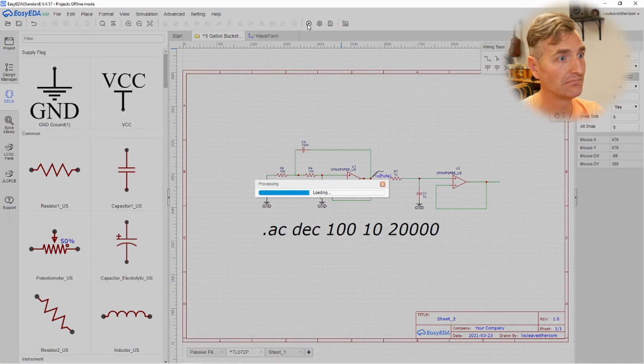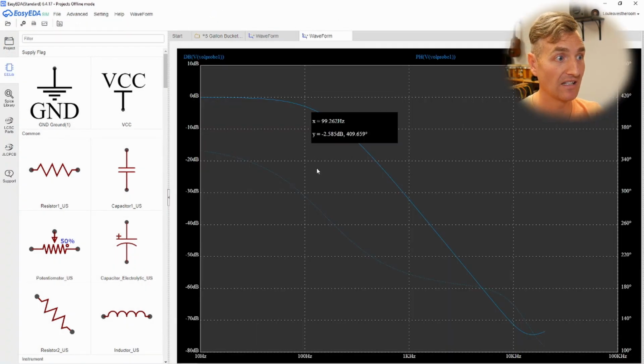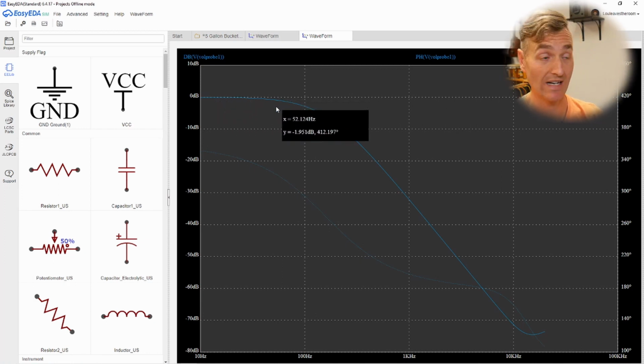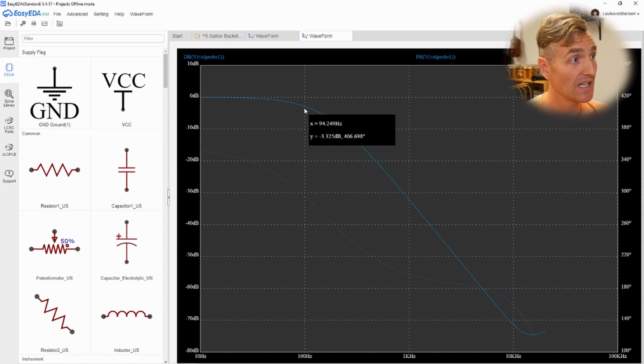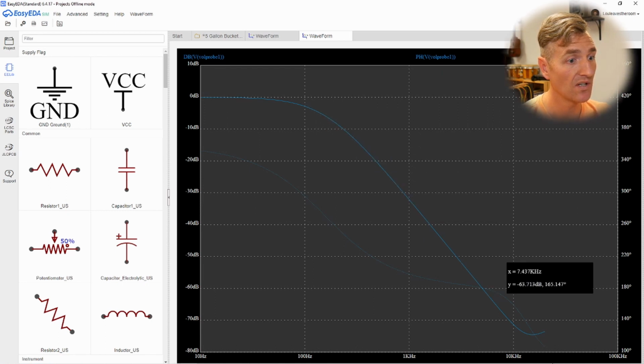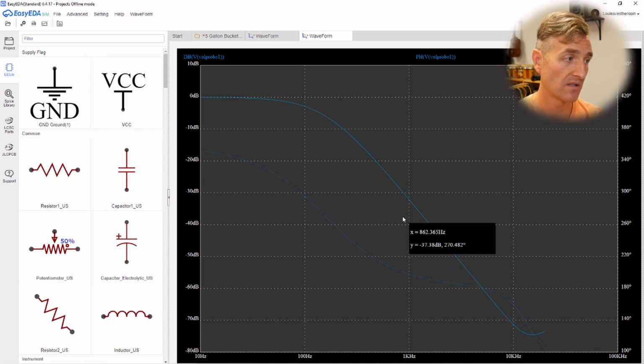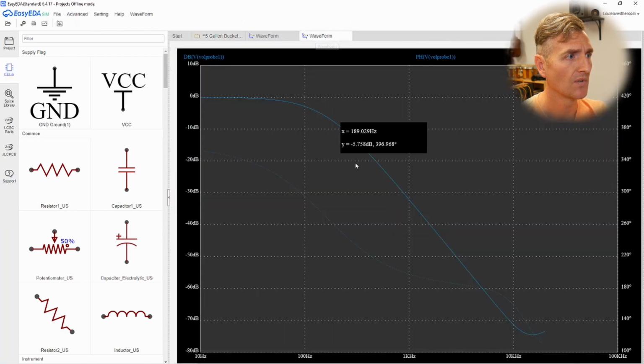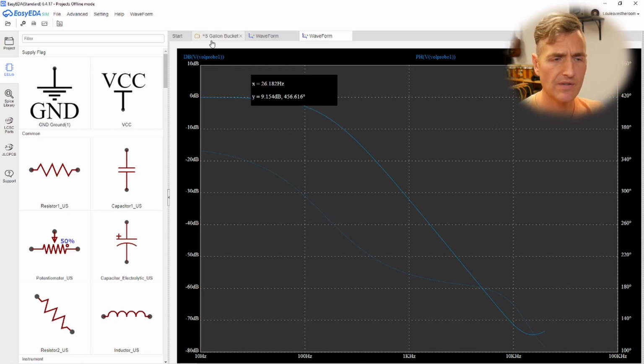I don't know. I'm again, O-scope wizard, not EDA, easy EDA wizard. Just trying to use the tools I have, like any engineer. Okay, so this guy, according to this, should get out to about 100 hertz and then roll off pretty steeply. So it's a second order, so it should roll off at about 40 dB per decade. What did we say? 100 hertz, somewhere, 100 hertz.